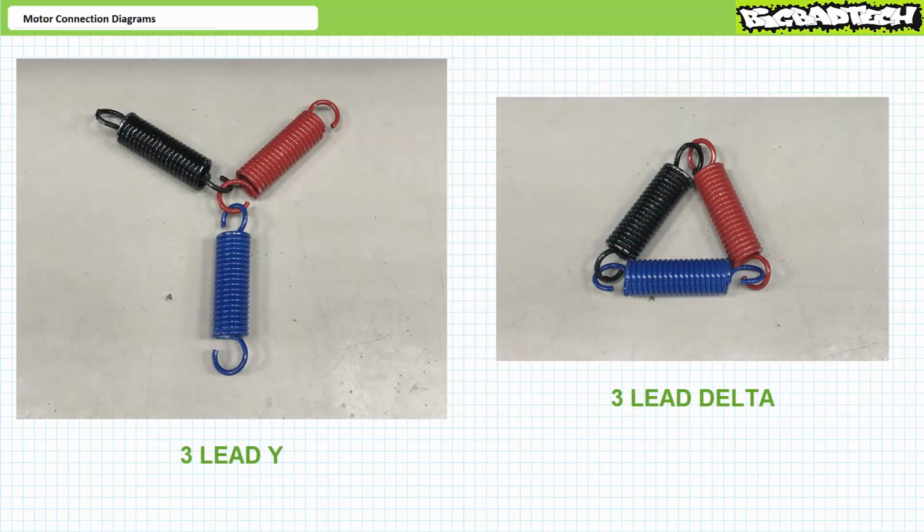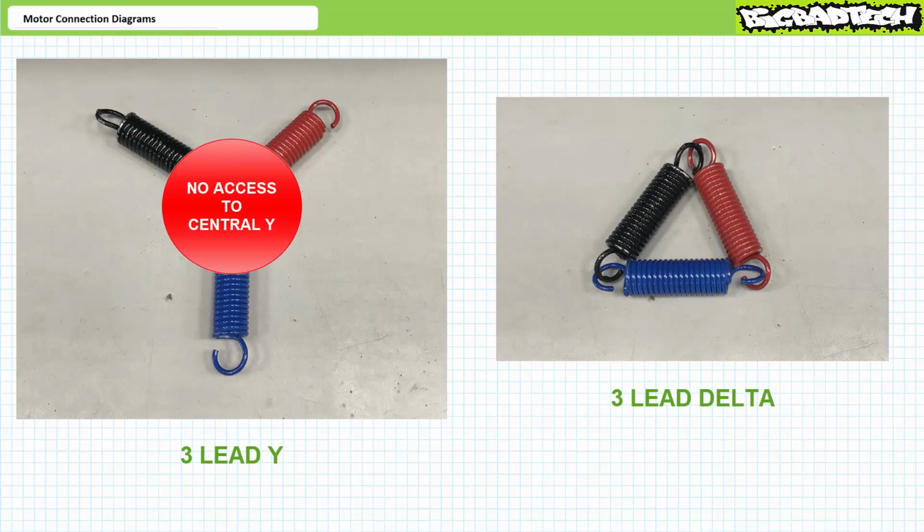While we've got these visualizations right in front of us, let me make an important observation about electrical instrumentation and 3-phase AC motors. These are 3-lead motors, and one does not ordinarily have access to the internal connections and individual windings. This implies certain electrical properties might be easier to obtain depending upon electrical configuration, and others less so. Allow me to demonstrate. As you are no doubt aware, voltmeters are placed in parallel with the item under test. A 3-lead Y configured motor typically hides the central node inside the motor. Thus, it is ordinarily impossible to measure voltage across an individual winding.